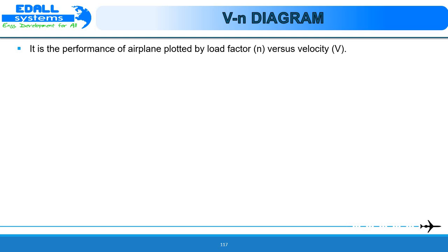We might find a Vg diagram in our flight manual if we are flying a high-performance fighter. The Vg diagram leads to cornering speed that allows us to extract maximum performance from our aircraft without breaking it. The operating flight strength limitations of an aeroplane are represented in the form of a Vn diagram. This chart is usually included in the aircraft flight handbook in the section dealing with operating limitations.